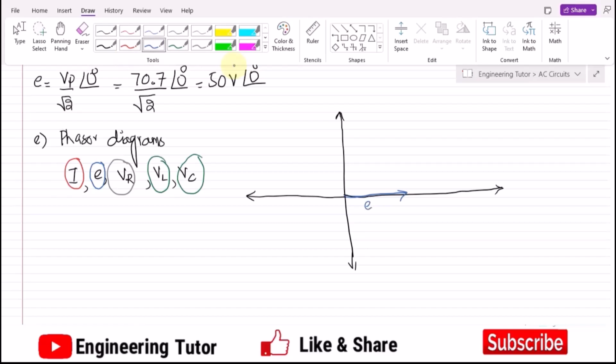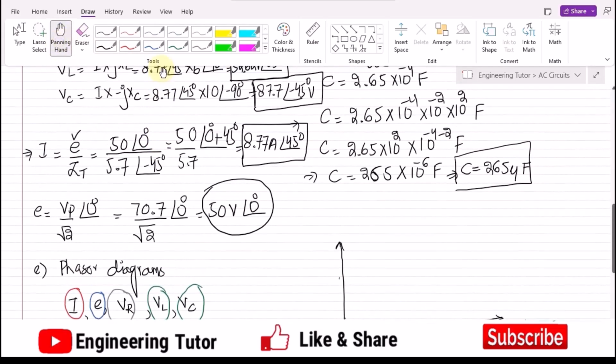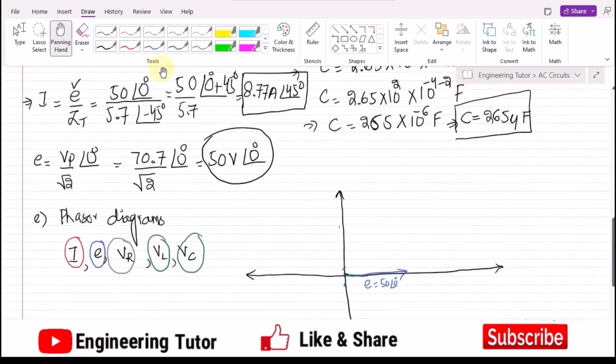This is E, and E is 50 and 0 degrees. So after plotting the phasor diagram of the total voltage here, let me plot the value of the current. The value of the current which we have found here is 8.77 amperes with the phase angle of 45 degrees. So the angle here is plus 45 degrees. Okay, this is the current, and the value of current is 8.77 amperes.